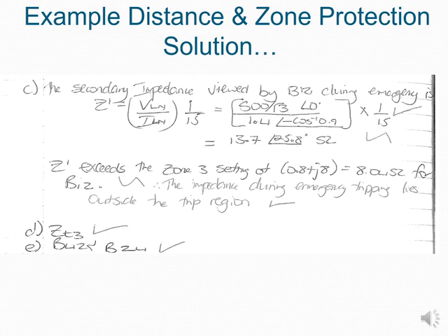So you would not be able to have an emergency situation of more than 500 milliseconds, which is really half a second, if you had no communication link in your lines, and only 120 milliseconds with a communication link.